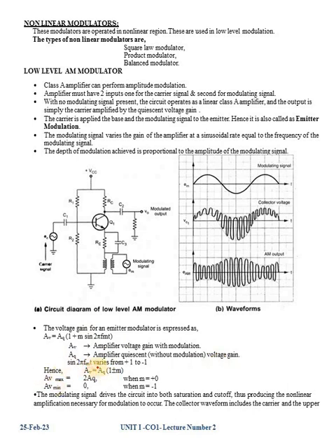We know that sin 2 pi FMT varies between plus 1 and minus 1. So when you substitute these values, we get AV as AQ into 1 plus or minus M. So AV max is equal to twice the AQ when the modulation index M is 1. Similarly, AV minimum is equal to 0 when M is equal to minus 1 in the above equation.